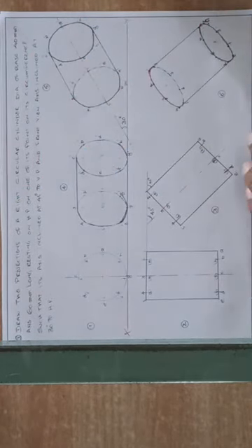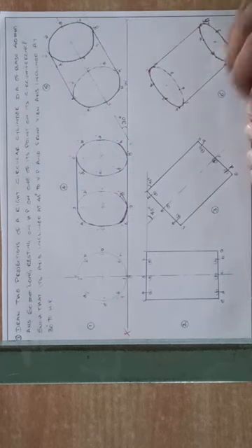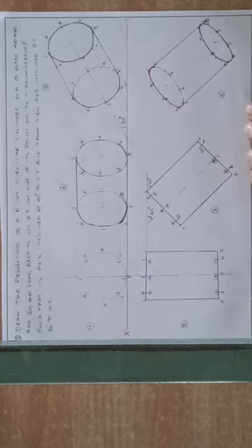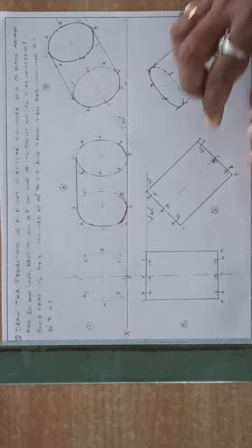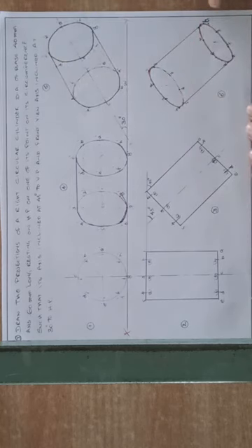Then again the same procedure, projections downwards, projections horizontal. Here also I suggest you project the first top face downwards, then the top face horizontal lines. Mark the points carefully, because here the lines will be very close. Be careful in marking the points and make a thick line, because when you observe from the top, you can see this face, make a thick line.